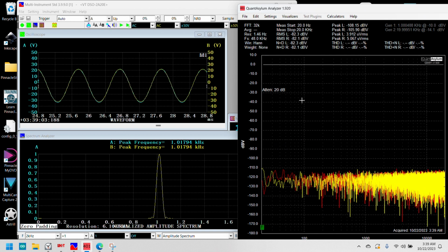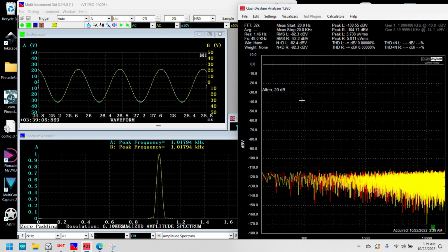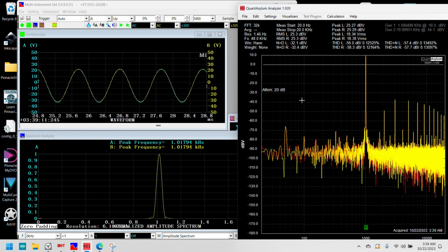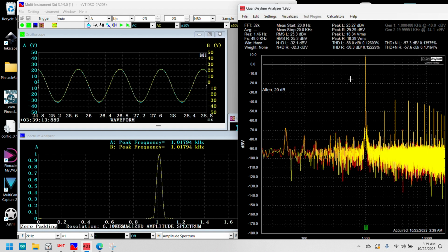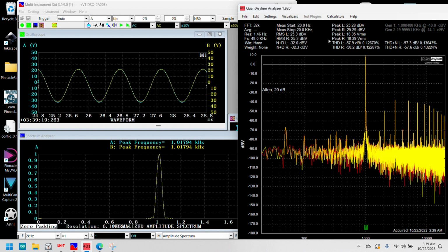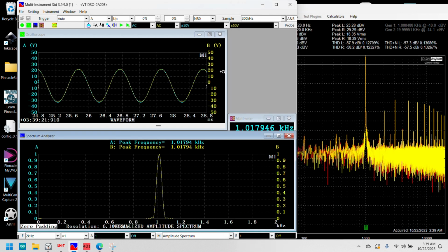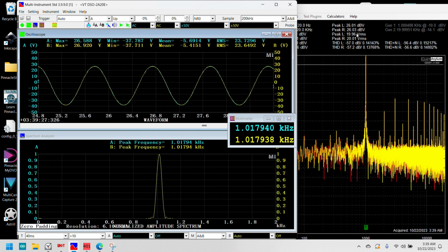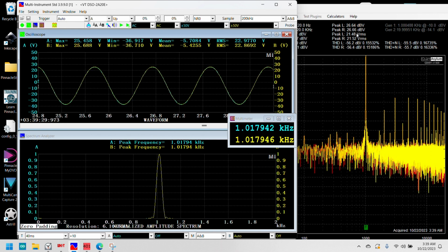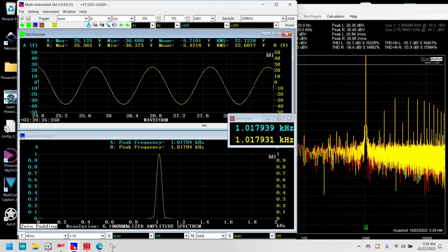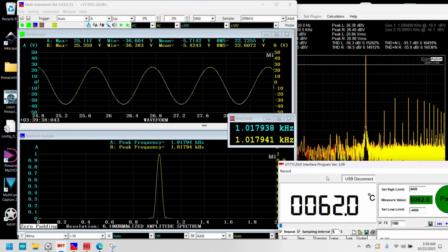This is actually light, guys. No trick right now. So I'm going to put an input right now. That is the maximum input for the QA401, 20 volt RMS. Now, if I say in here this is 18, what we can read in here is, what is it? All right, a 20. So I'm going to trust the QA401, 21. There you go, 20. And let's just watch the temperature because that is very important. Now it's 62 degrees centigrade.